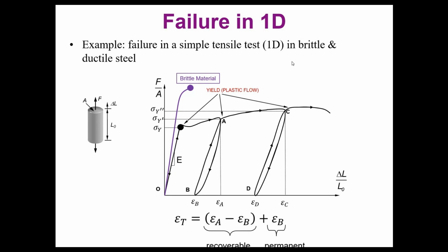Maybe non-linear elastic, because evidently this is a curve, it's not a straight line, but you will be able to recover all the deformation. So this is the reason why there is a distinction between the failure for brittle material and the failure for ductile materials. So the plastic theory will allow us to capture all the behavior after that point, the yield point we have defined for the ductile material.